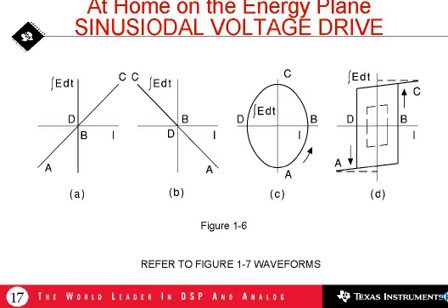What's the next one? Here we have another straight line, but it's oriented at a different angle. It turns out that this device shown here would be a capacitor. Straight line again, as we traverse that characteristic, there's no loss. It's a lossless capacitor. In the characteristic shown in A, the inductor, the relationship between the current and the voltage applied to this device is, of course, 180 degrees out of phase with the comparable waveforms in the capacitor shown in B.